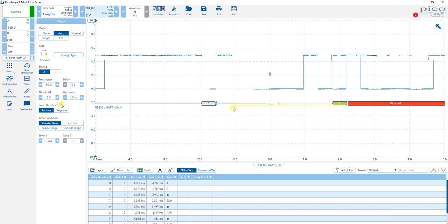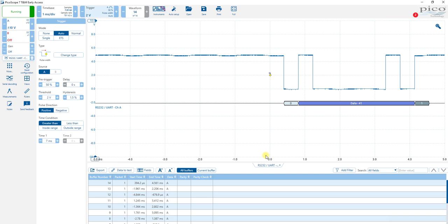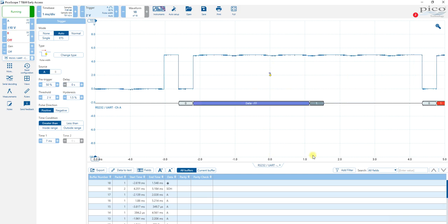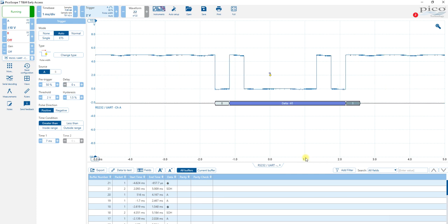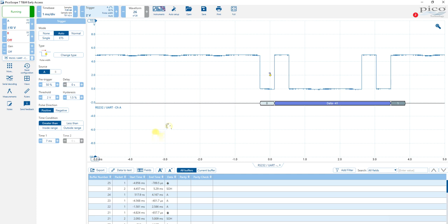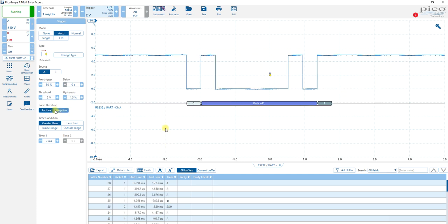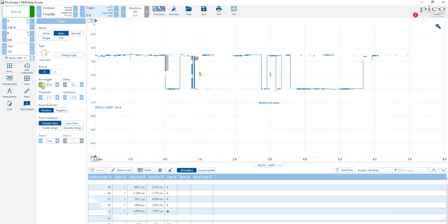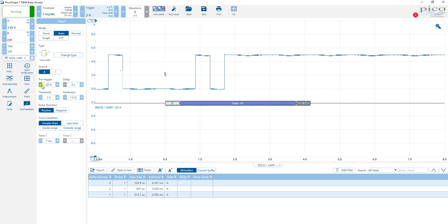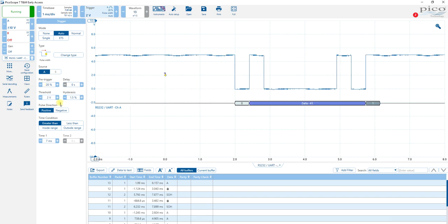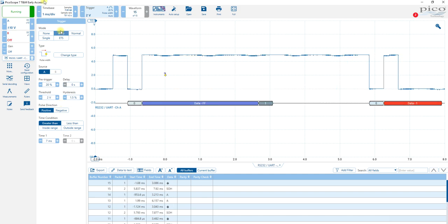So the next thing I'm going to do is the trigger point right now is at 50%. You can see it right here. And this time indicates a 1 millisecond division. But I want to have it trigger maybe at 20%, which is right at this point here. So I changed the pre-trigger to 20, which I've just done. Okay, now you can see that the trigger line is there. And it is triggering after a long period of delay, but let's have the time base change.